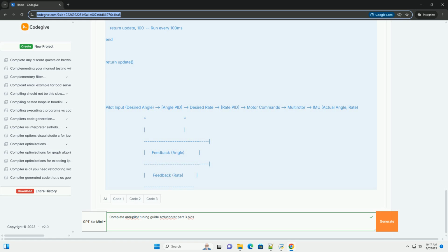Initial values. Tuning roll/pitch rate PID, iterative approach. Increasing P. Adjusting I. Tweaking D. Tuning your rate PID. Special considerations for yaw. 5. Tuning process, angle PID loops: connecting rate and angle loops. Adjusting angle P, the primary controller. Using auto-tune, use with caution. 6. Common issues and troubleshooting.